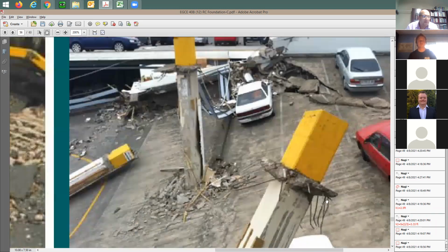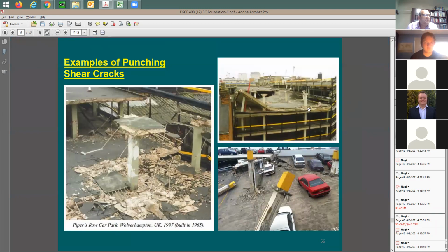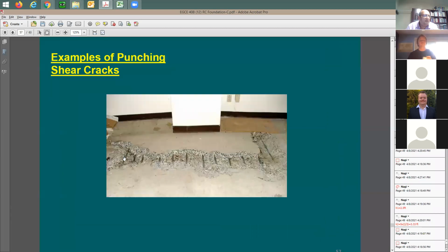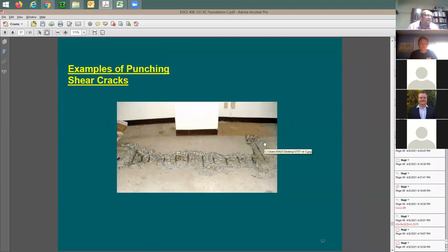And this piece also. Look at this piece here. So the same thing here. You look here after they remove the flooring, like the carpet or whatever that used to be there. Now look at the slab and look at this. It looks like kind of a circular shape, right? This is on the perimeter of the column, that was about maybe 16 inches. So now we understand that we have a punching shear issue in this column. It needs to be fixed for this existing construction.